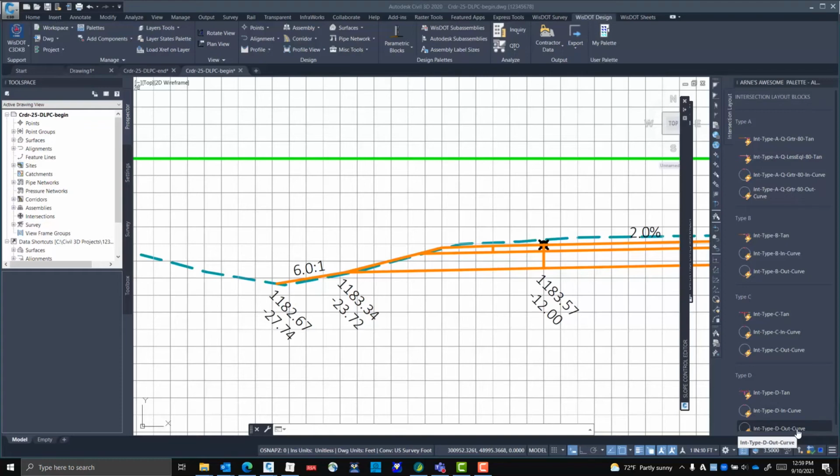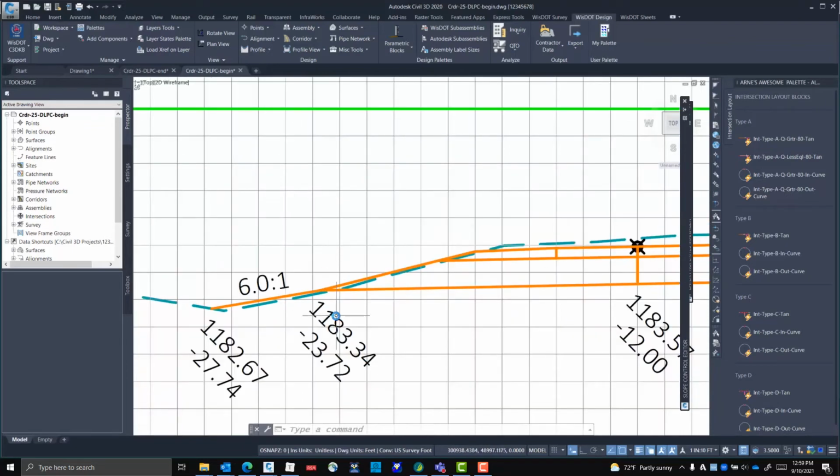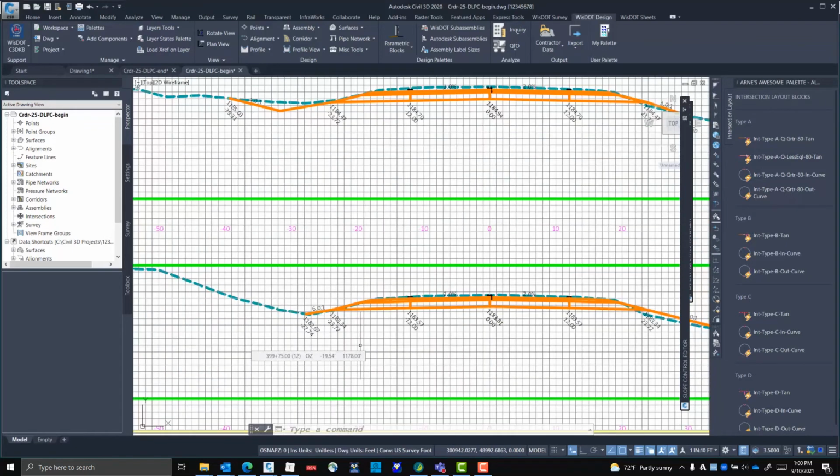And one of the things that happens a lot of times is the closer your subgrade shoulder point is to existing ground, the less often the default logic works: if I'm above ground, go down; if I'm below ground, go up. What we decided is that our users need control over that.